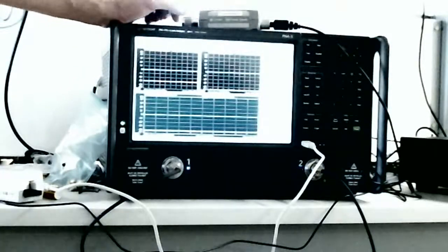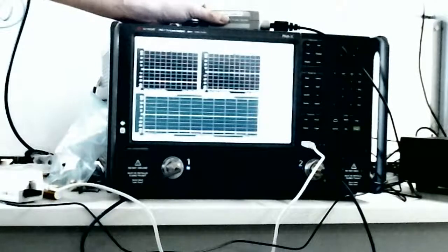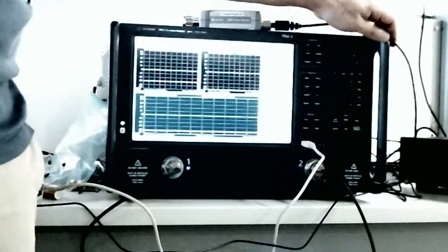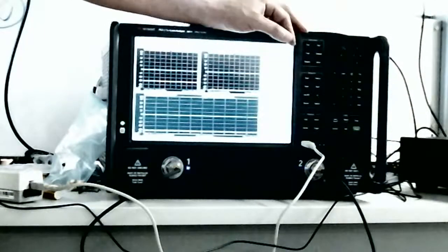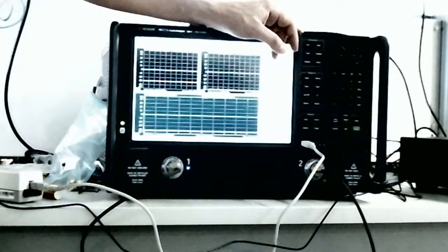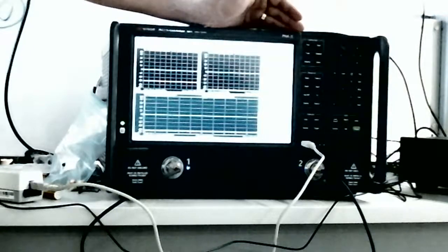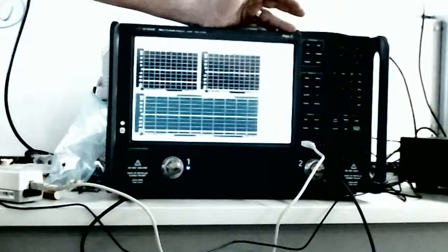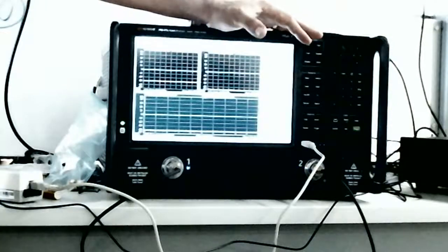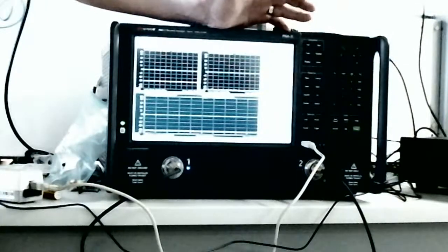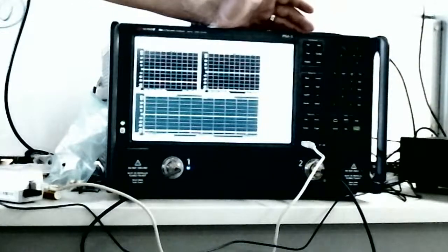So how often are you doing amplifier tests then? Not very often? Okay. So for the antenna, we just make the S11 measurement. That's pretty much it. Antenna measurements are usually pretty simple. The only time it gets a little bit complicated is when you're doing a radiated pattern test, right? So do you guys have a positioner and an antenna chamber?